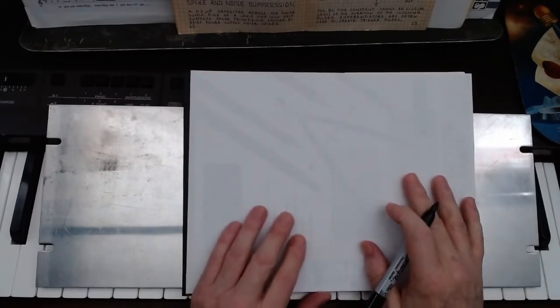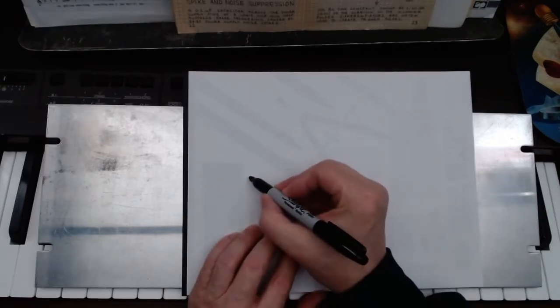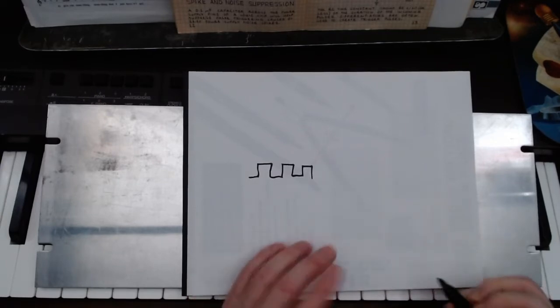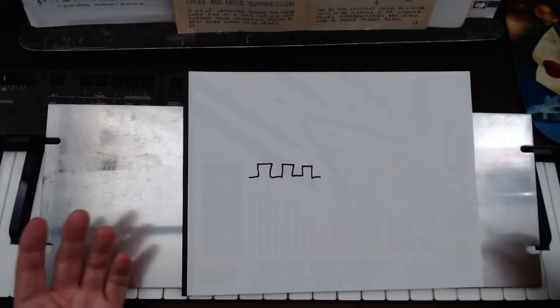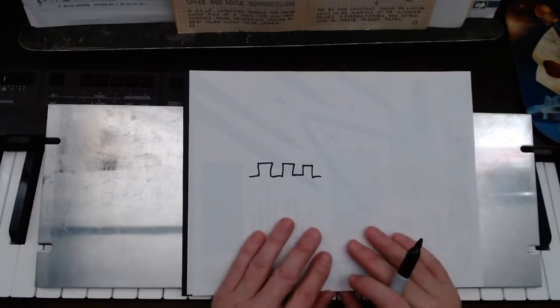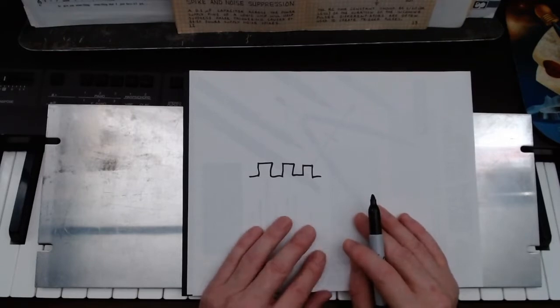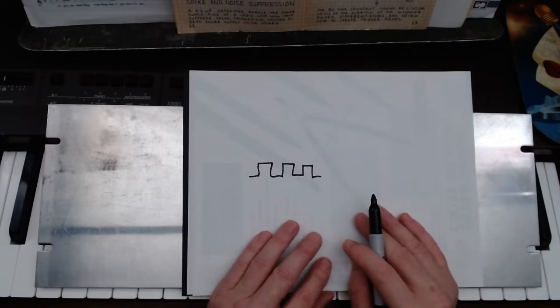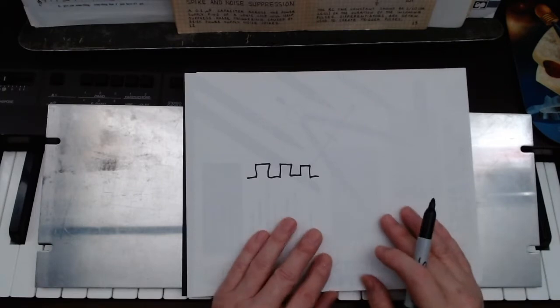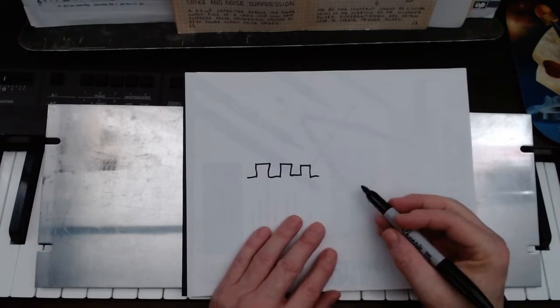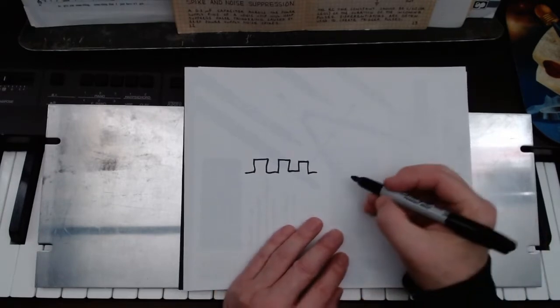Okay, so most simple oscillators are going to generate a square wave. Now, this is only useful for certain types of tones. By itself, it sort of gives you a clarinet sound, but we might want it to be a little different. We might want a different wave shape in order to generate, say, a flute or a diapason tone or a string tone. So there's a circuit called an integrator,